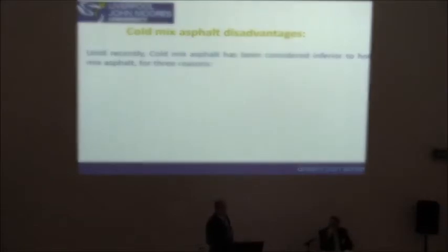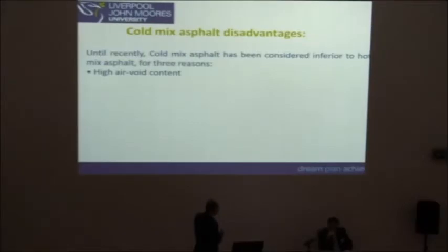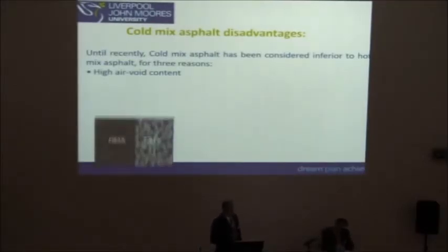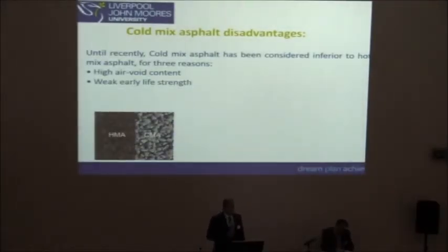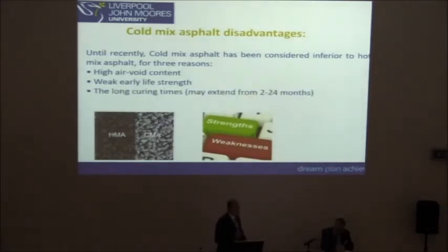But there are drawbacks for the cold mix. It suffers from three disadvantages: higher air voids content in the compacted mixture, weak early strength, and long curing time. It will take from 2 to 24 months to get a good stiffness compared with the hot mix.